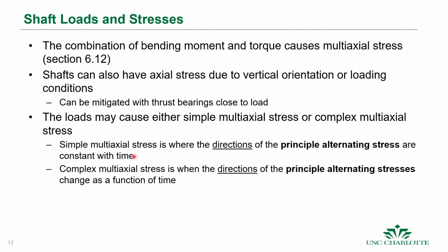That means if you were to plot the principal stresses while the machine is rotating, the directions of those principal stresses essentially stay constant. Effectively, the load cycling is such that it doesn't change the direction of those principal alternating stresses.